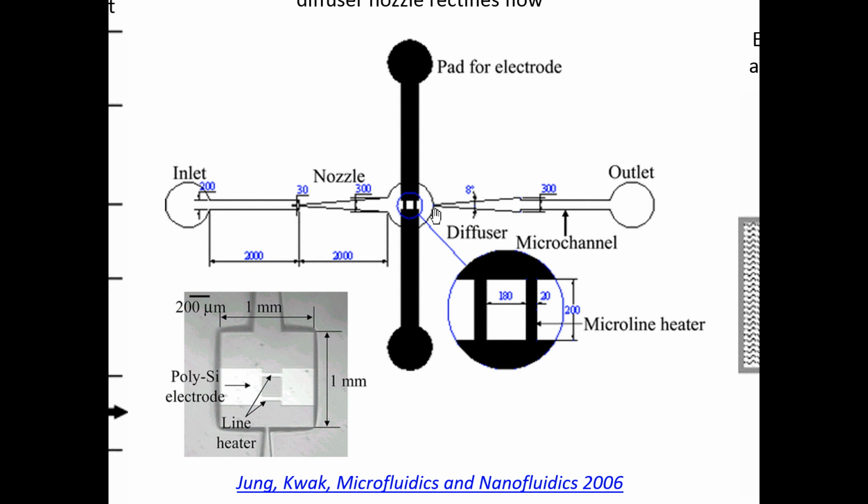If you have a really narrow line, the electrical resistance of that region is large, so there will be more joule heating in these thin regions. From the purely physics standpoint, if you have electrons flowing from this top pad to the bottom pad, this constriction here, you're forcing all those electrons to go through a very narrow region. That actually generates heat. So this is called a joule heater.